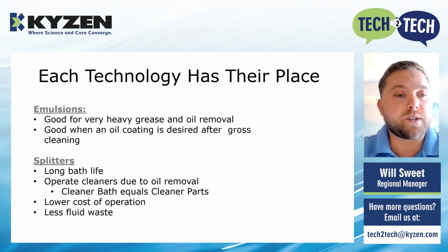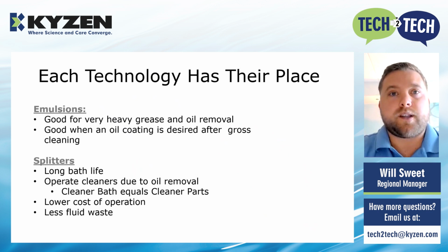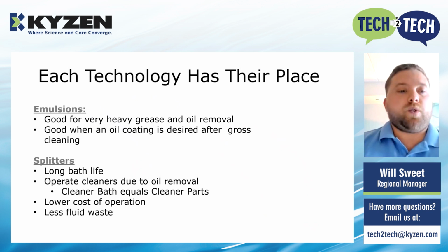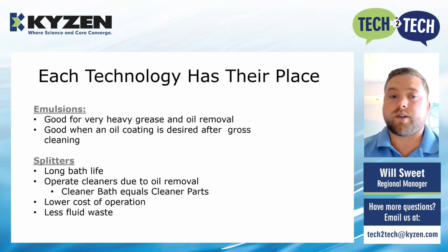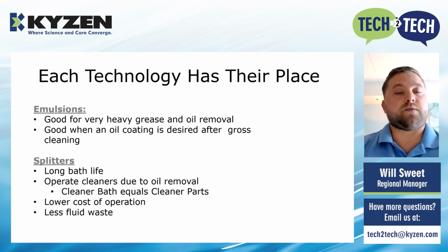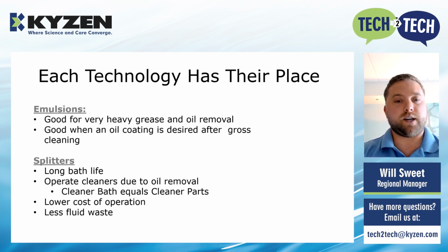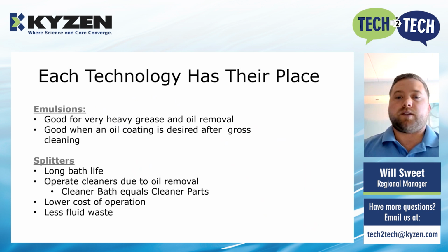So then moving on to the splitters, much longer bath life, because again, that oil is not going to be mixed in with the entire bath. You're able to remove it from the top. You can operate cleaners longer due to oil removal. Cleaner bath equals cleaner parts. Here's something we like to say at KYZEN: you're only as clean as your final rinse. Lower cost of operation because you're not going to be throwing away as much chemistry as often, leading into less fluid waste. So there are several cost savings there. Cleaner parts, and it really seems to be a better process over time.